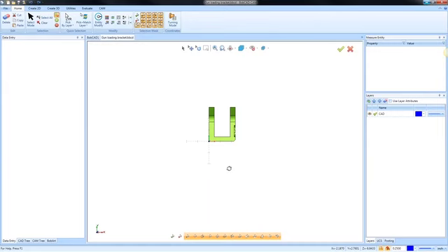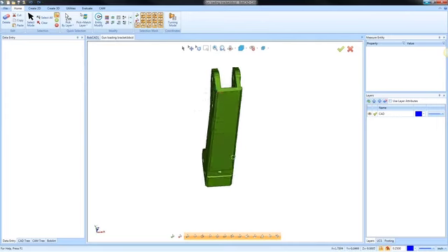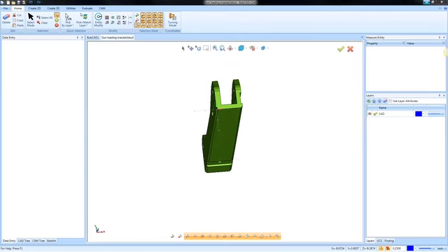There are a number of different reasons why that happens. It really comes down to what design package the software was used. Like this one was done in SolidWorks, so it comes in the wrong orientation. As a general rule of thumb, I like to rotate that geometry to get it flat in the XY plane. It's not a necessary step, but it is something that I do often.